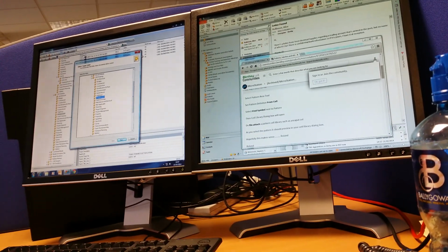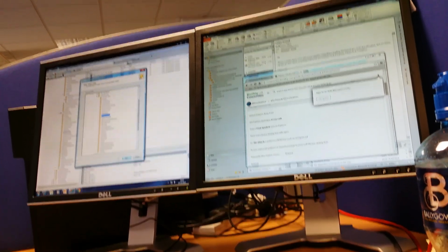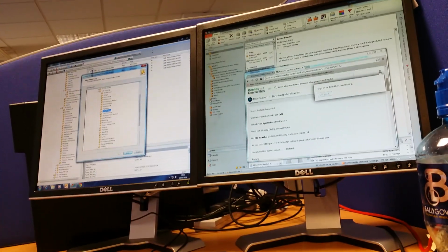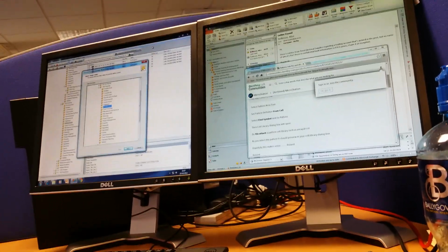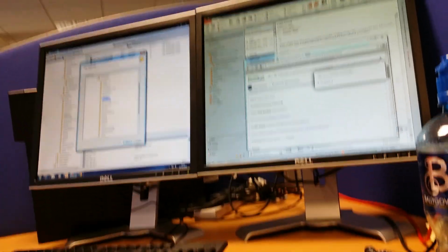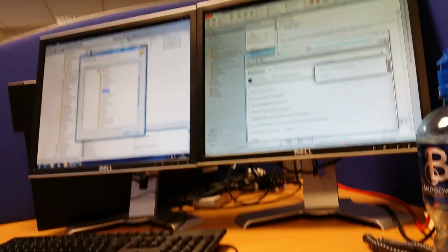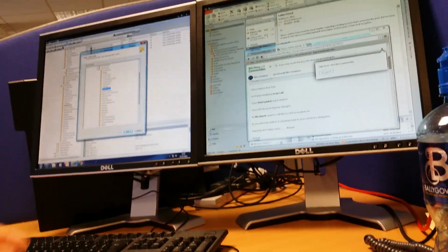Now this next one's going to be slightly more awkward for you, because we've broken the OS and the LiDAR down into short sections, because otherwise the OS map initially was about 40 meg, which is way too big. Because we're already in there, all you need to do is change the path. You don't need to delete them and bring them back in.